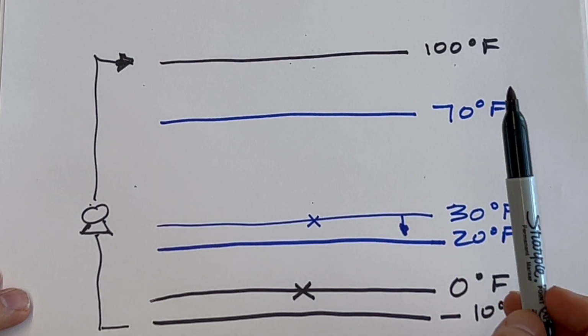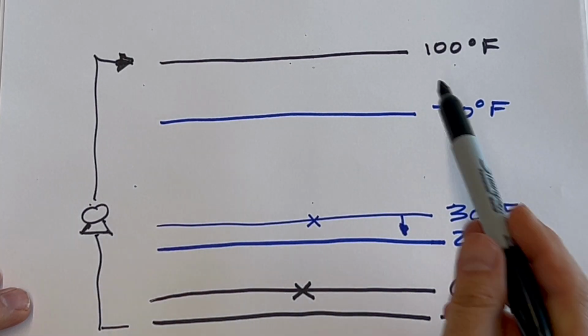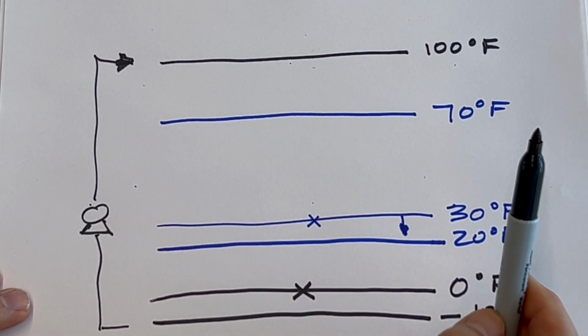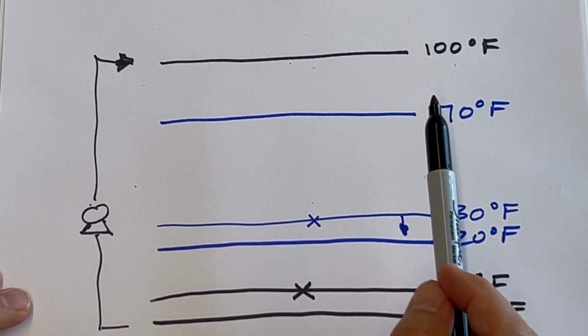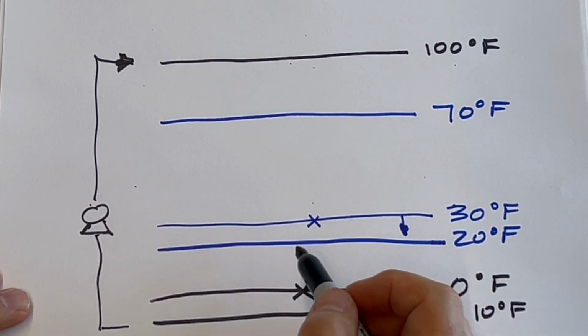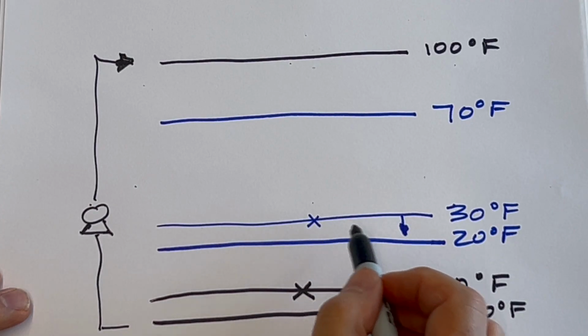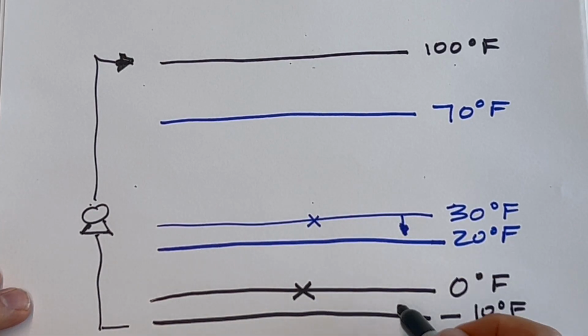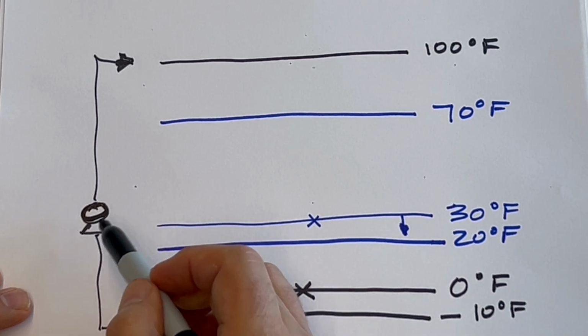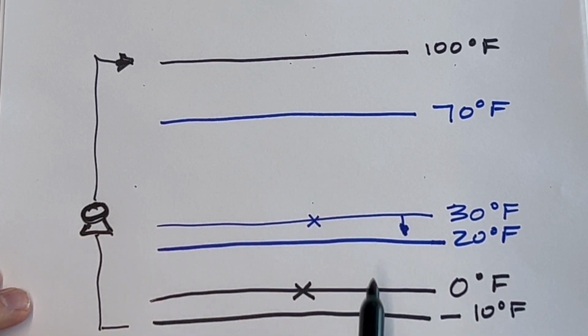So the capacity required goes up, but the capacity that the heat pump provides goes down, which is why we need to speed it up with a variable speed compressor. The key thing is that when the outside temperature goes down, the temperature of the refrigerant goes down, the compressor needs to work harder, and the efficiency goes down.